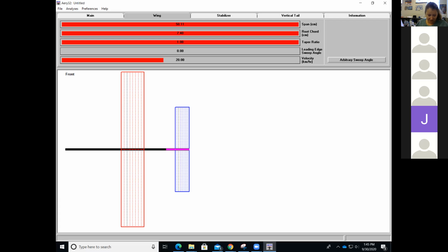If you were here and you had a long meter stick or something, I could maybe cut it for you in the laser cutter. But if you're doing it at home, keep it simple, okay? Keep the thickness of the wing as it is. That way, you do not have to cut all the way across. If you want to add a taper, cutting 2 triangular pieces would be easier to do.